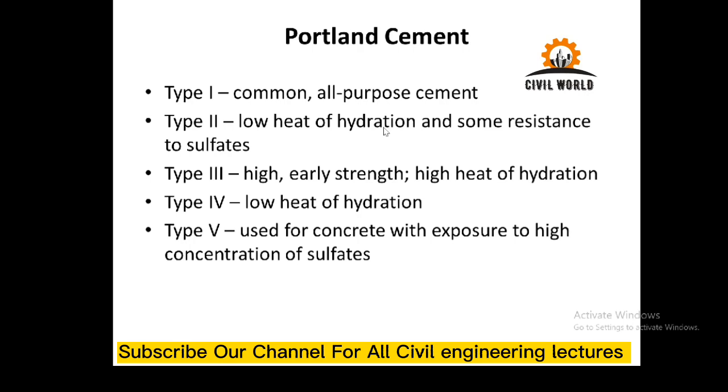In case of type 2 cements, which are low heat of hydration cements, they also offer some sulfate resistance. Sulfate attack is not desirable for concrete, because once sulfate compounds seep into the concrete, they form new compounds which have more volume compared to the original volume.